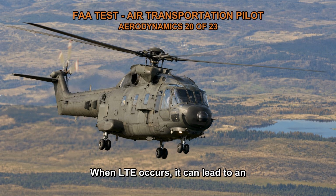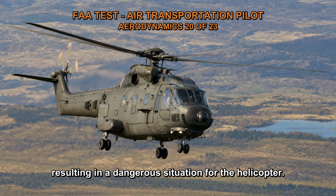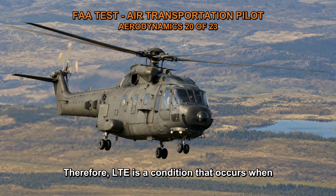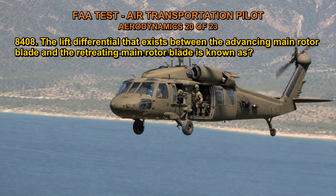When LTE occurs, it can lead to an uncommanded yaw or loss of yaw control, potentially resulting in a dangerous situation for the helicopter. Pilots must be aware of the conditions that can lead to LTE and take appropriate actions to prevent or recover from it. Therefore, LTE is a condition that occurs when the flow of air through a tail rotor is altered in some way.